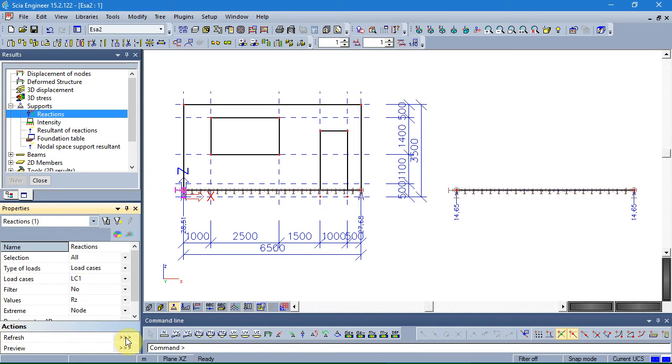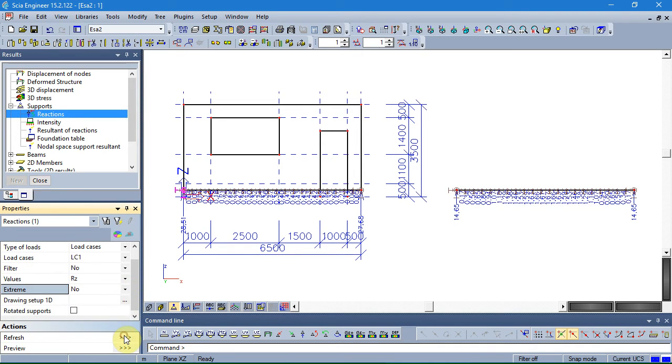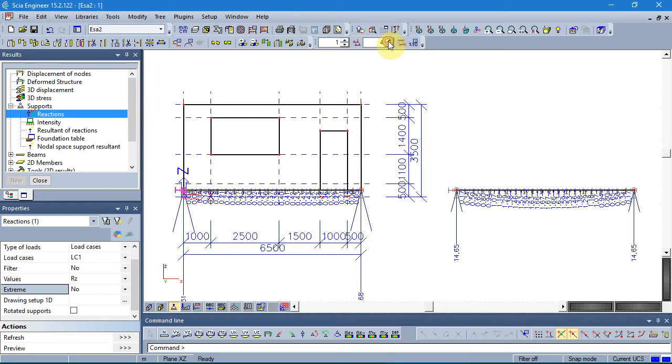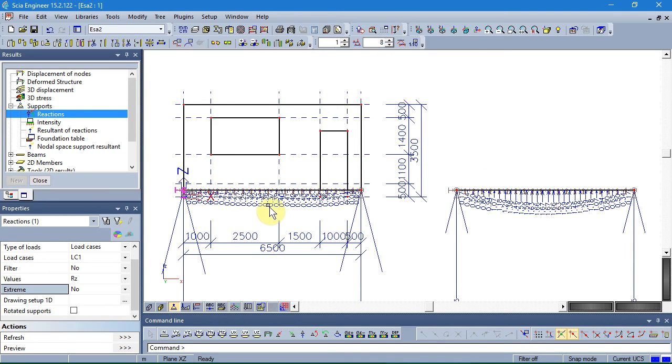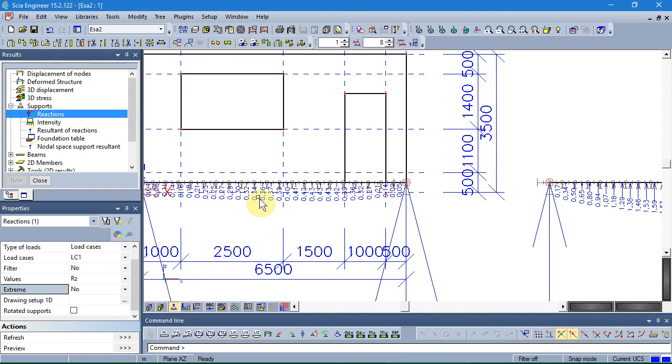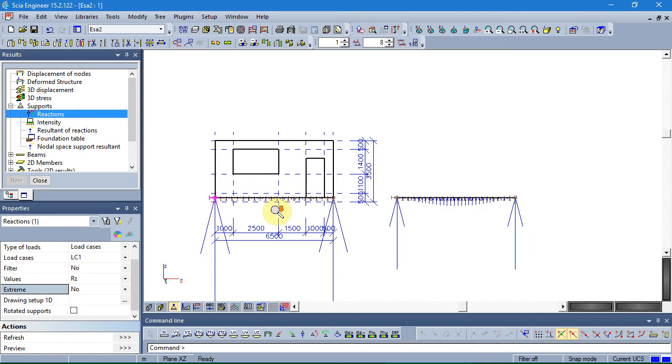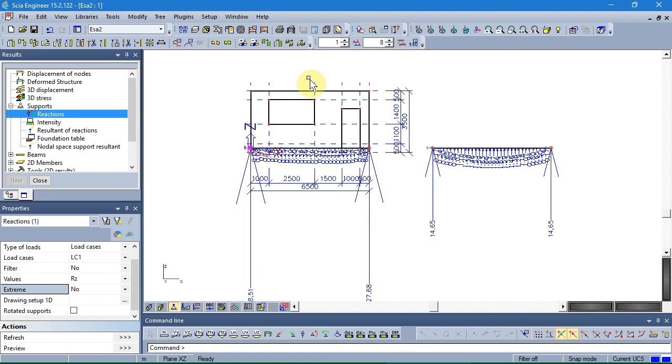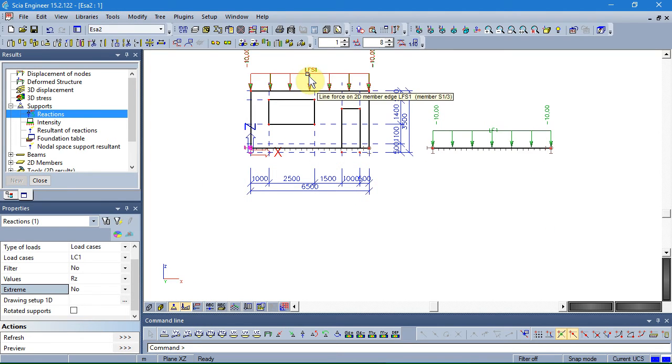Reactions. Okay. 28 kilonewton and 14 kilonewton. And if we look also at the reactions between the points, we see 1.6, and here is only 0.3, 0.4. Because in this wall, before the load comes from top to bottom through the wall, it will be distributed to the points which are stronger.